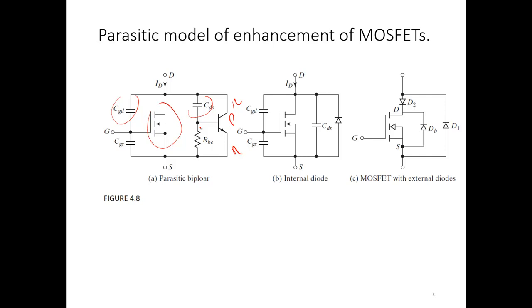What happens very often is that you're going to find this is like a diode, from P to N. Internally, the device has a diode in the reverse direction. The forward direction is a switch, the reverse direction is a diode. But what does it mean? It means that the device can allow current in both directions. And that is a MOSFET.